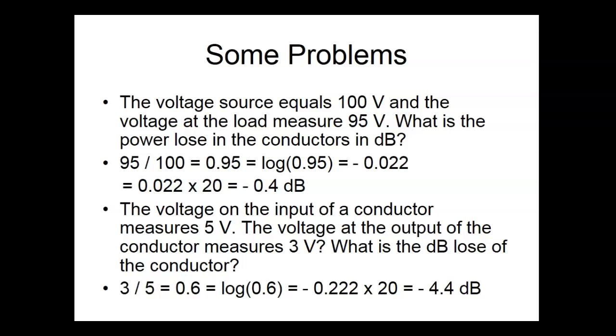Or we do it every once in a while to measure the differential. So, by the way, that's the way a ground fault interrupter works. It's measuring the differential between what we call the hot and the neutral. Those two currents should always what? Should always match. If they don't match, that means that other current is going somewhere between you and ground, right? You understand? If you get across the hot and the neutral on a power plug, the ground fault interrupter is not going to do anything. It considers you to be a light bulb. But if you get between the hot and ground, then it'll trip. Because now the current flow going on the neutral and the hot don't match. So that's all a ground fault interrupter is. It's just a current transformer. That's all it is.